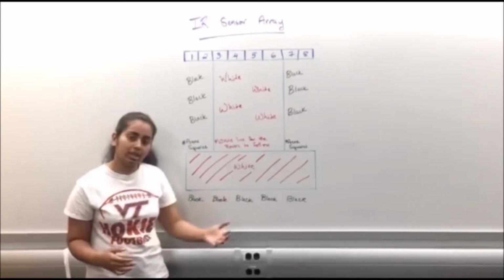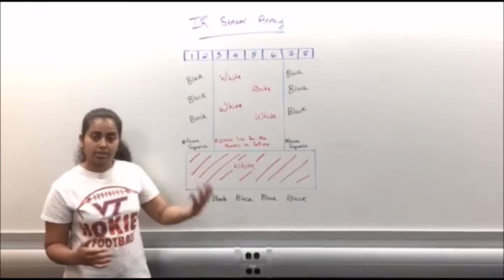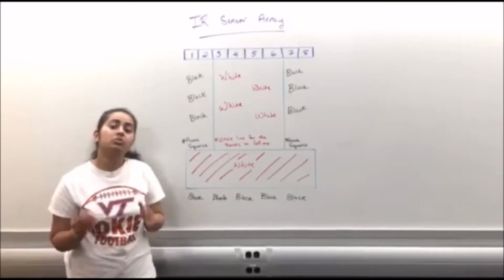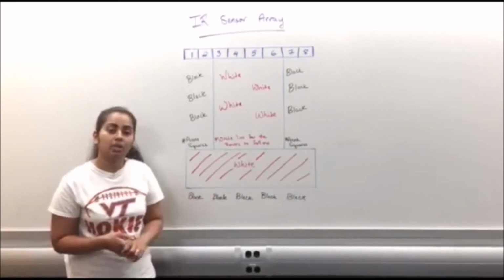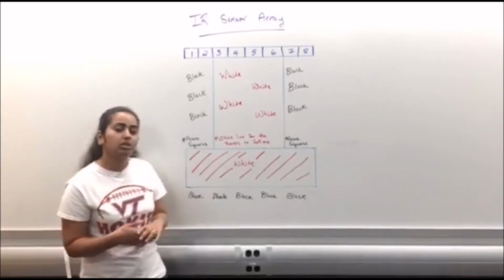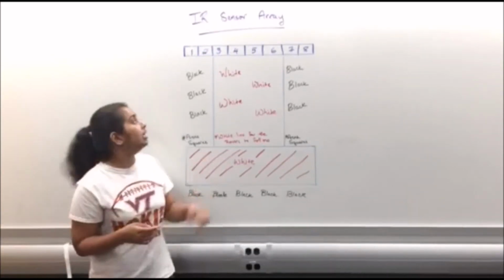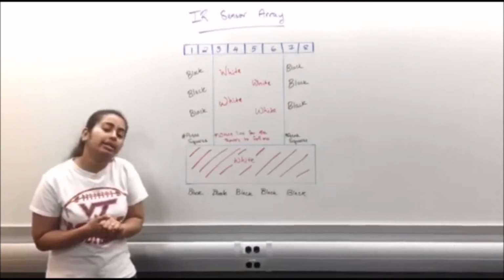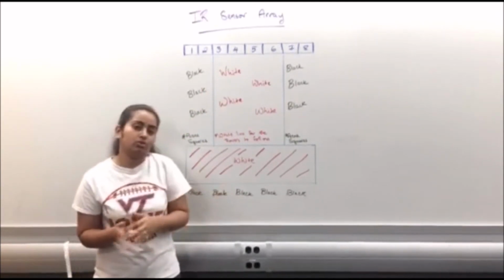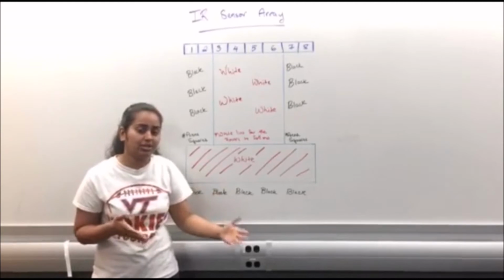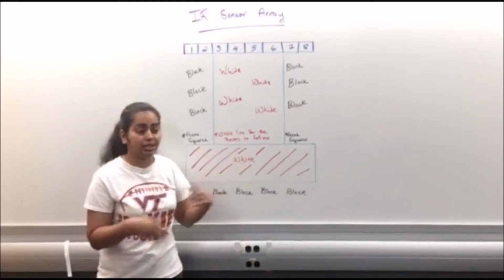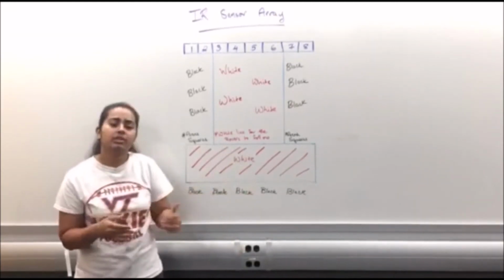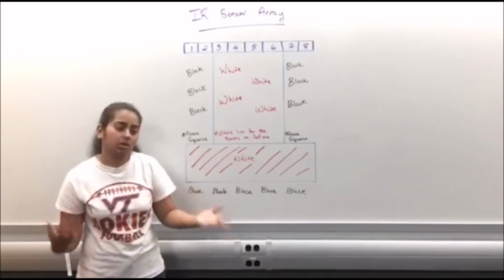Within the sensor thread itself, it interprets the sensor data it gets and determines where the rover is on the line. So for our situation, in order to be considered as following the line, the sensors 3, 4, 5, and 6 have to be seeing white. And white is considered as a smaller number, so if it takes less time for the capacitor to discharge, then it's considered as seeing lighter colors, like white. And if it takes more time, then it's considered seeing darker colors like black.